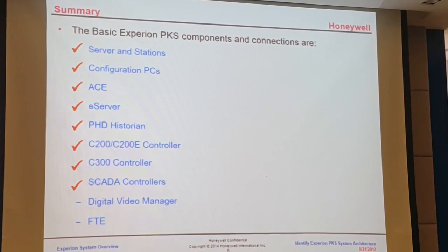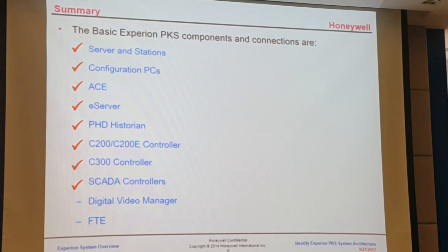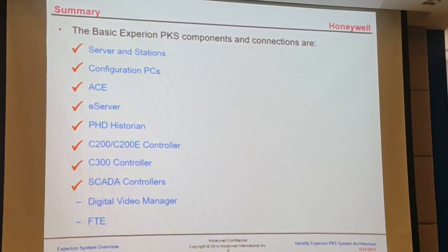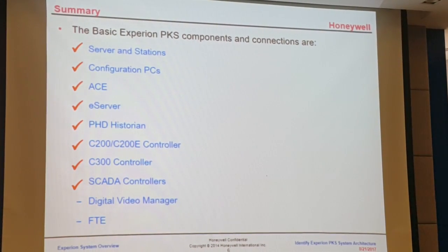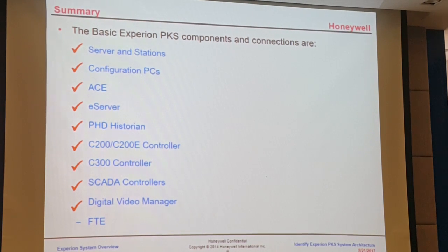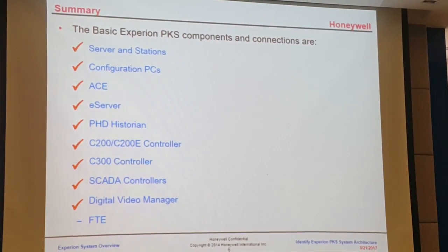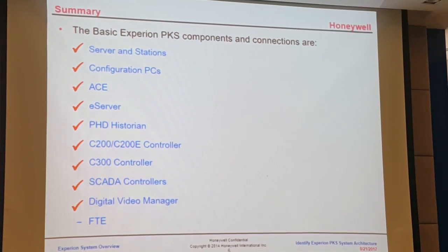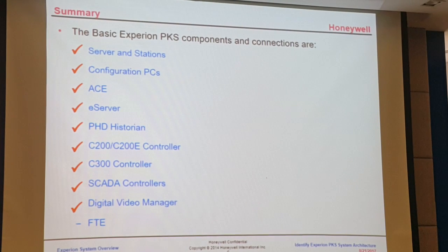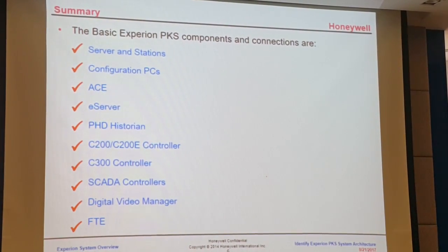We use Experion to map for supervisory control and data acquisition. We've got the DVM, which supplies live video to the station and operator screens. And we finally hook everything together using Fault Tolerant Ethernet, or FTE.